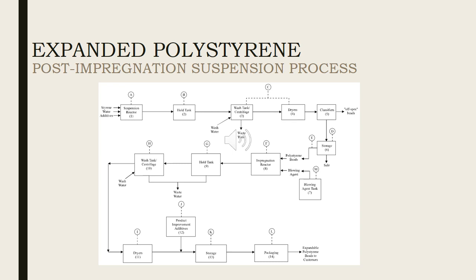The size of the product beads depends on both the strength of agitation and the nature of the monomer and suspending agents. Between 20 and 70% conversion, agitation becomes extremely critical. If agitation weakens or stops between these limits, polymer particles may agglomerate, followed by a runaway reaction.